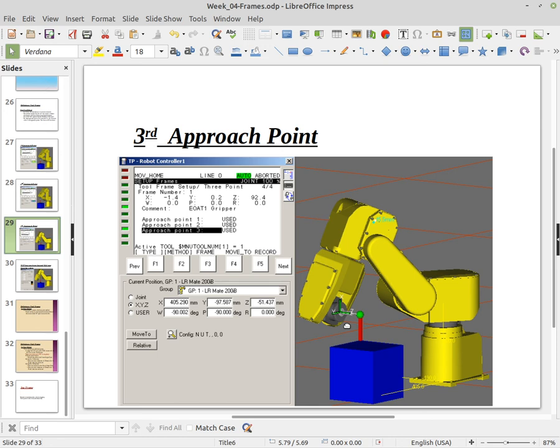The 6-point method, what the other 3 points are for the 6-point method, is they allow you to redefine the directions of X, Y, and Z. Now, normally by default, when you're in the tool frame reference, plus Z is, as shown in this slide, coming straight out of the pointer of the robot. However, it doesn't have to be. So what the 6-point method allows us to do is redefine an X, Y, and Z direction for our tool frame.